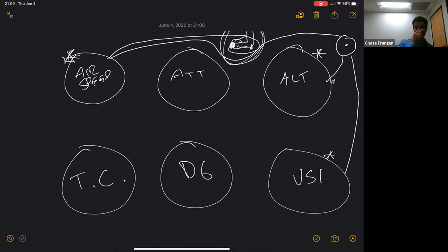So those are some of the common errors that you see if you have some blockages in the pitot static system. Those three instruments are driven off of the pitot static system, both ram air and static air. We can get into alternate static, what happens if the static port clogs, you can break your VSI, stuff like that, or turn on alternate static if your airplane is so equipped. But that's the pitot static system. Any questions on that?